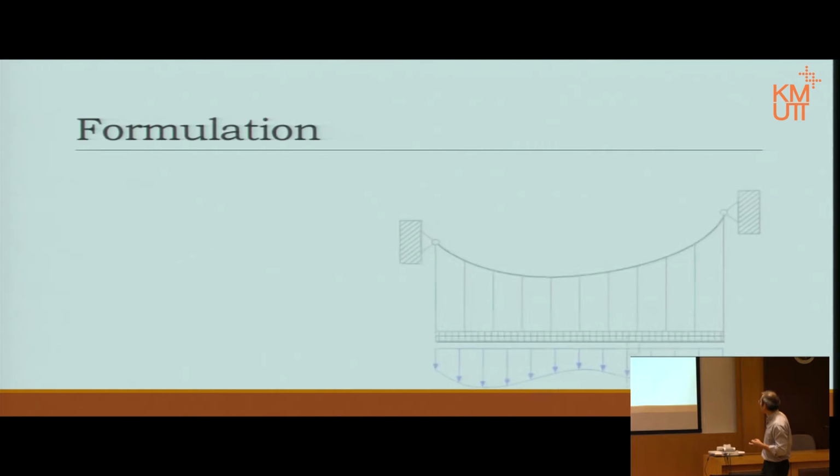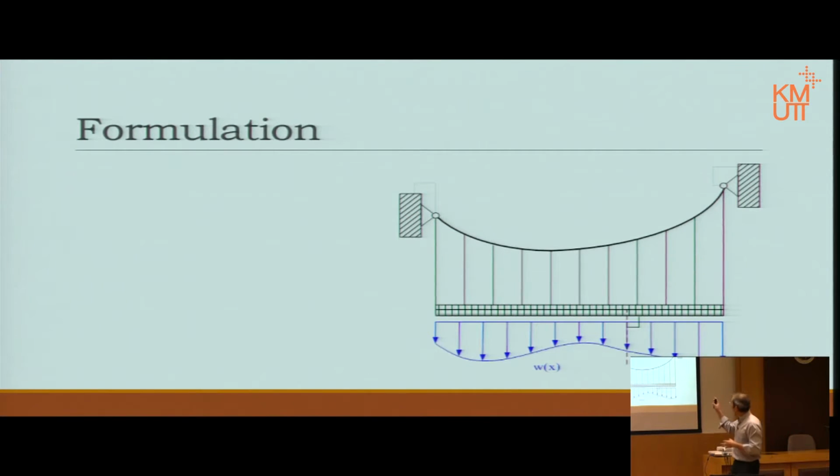Now the way we formulate it. This is the idea. The two supports, although drawn as if having a vertical wall, don't actually mean that. It just symbolizes the pin support, meaning at that point, we know that cable only takes tension, and cable doesn't resist any bending moment. Therefore, the constraint allows rotation at the support, whereas it doesn't move either left or right or up or down. The cable should stay there at the support. It doesn't actually mean we have to hang it on the wall. It could be a column upwards, but the pin support type is still there.